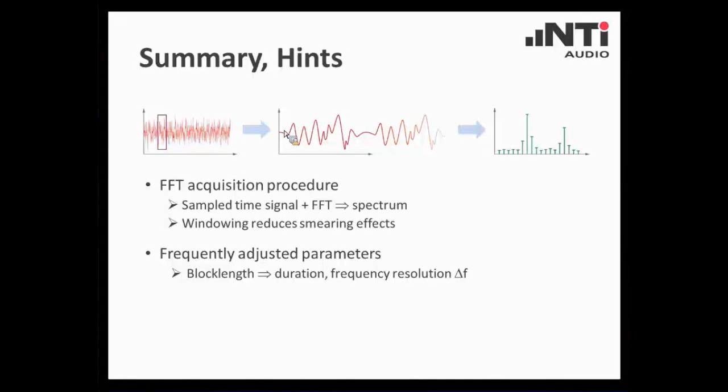Typically, you may first adapt the block length. Keep in mind, a higher block length means a longer duration, so the refresh rate of that FFT will be slower. On the other side, a higher block length also means a higher frequency resolution. The delta F becomes finer, smaller. That is the balance that you have to find.